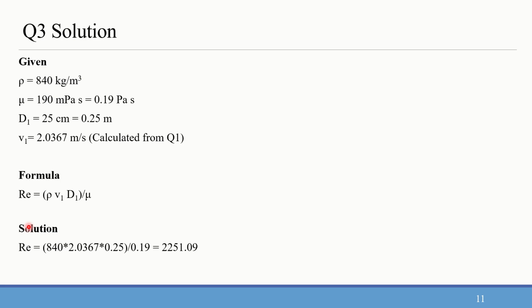So that's why we calculate the Reynolds number, right? To determine which regime of flow is happening: laminar, turbulent, or in the transition zone. Here it is less than 2300 in a pipe flow, so we can say it is a laminar condition. And what is Reynolds number? Reynolds number is the ratio of inertial force to the viscous force. So here the viscous force is dominating compared to the inertial force because velocity here is low, compared to the outlet, I mean to say.